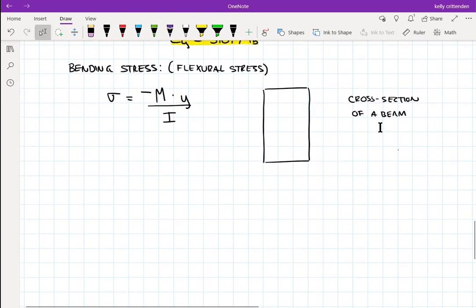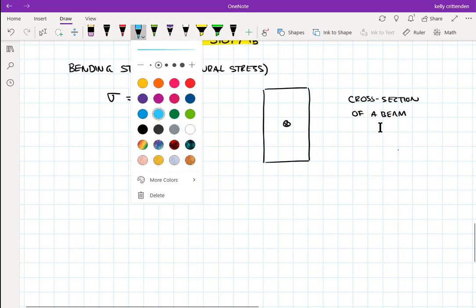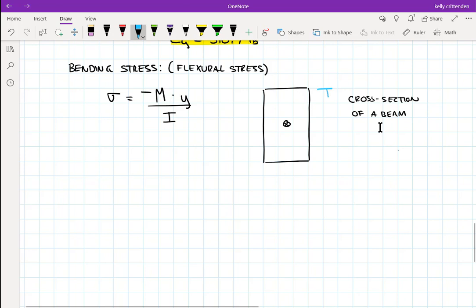So we know that the centroid for this thing, if it's a rectangle, is just right in the center of the height. So let's put numbers on it to make it easier to talk about. Let's say this is 6 inches, and we'll put the base on here of 3 inches, though we won't need it.